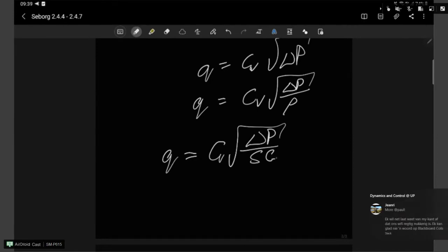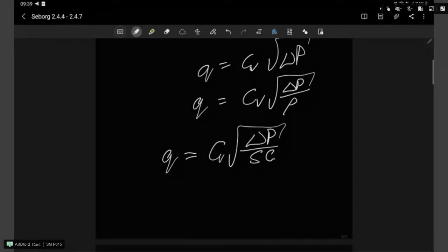The reason for that is because this value has been determined for water, the SG already relates that to some extent with water, because the SG of a liquid at least is obviously determined for the standard temperature and pressure density of water, which is 1000. Or not, can't remember. Normal temperature and pressure, standard temperature and pressure, whichever one. But in any event, the SG relates that, and that will solve your CV problem in this scenario. So please note that CV is not 100% dimensionless.